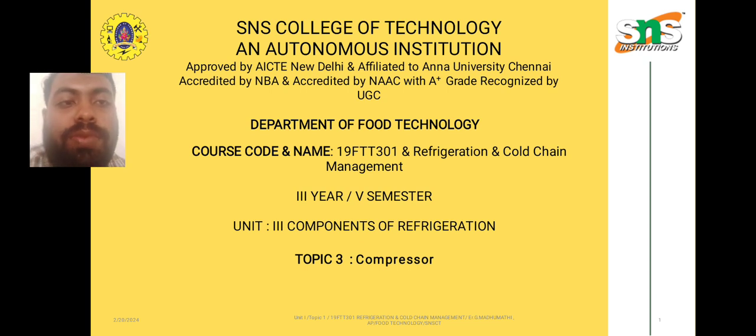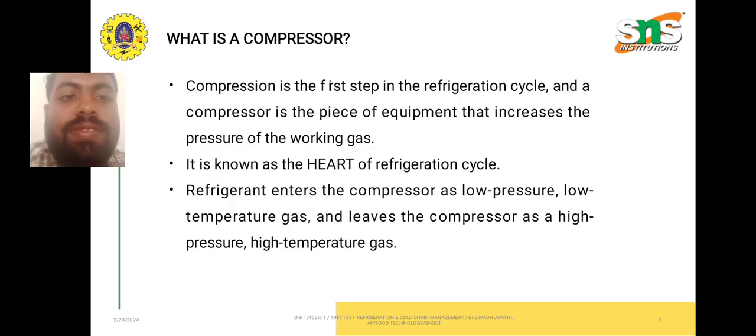Just a quick review. Compression is the first step in the refrigeration cycle, and a compressor is a piece of equipment that increases the pressure of a working gas. It is also known as the heart of the refrigeration cycle. The refrigerant enters the compressor as low pressure, low temperature gas, and leaves the compressor as high pressure, high temperature gas.